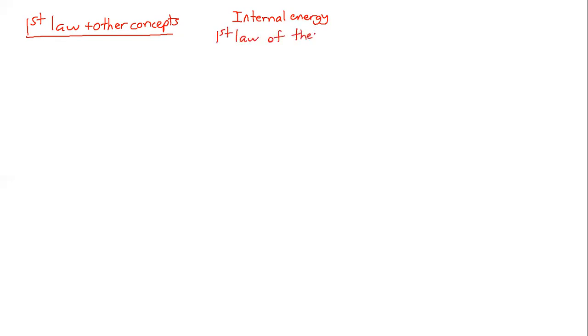is used in process simulation all the time. This is that energy is conserved. You can do energy balances for different types of systems. Aspen Plus actually runs on this. It runs on doing the energy and the mass balances into and out of the different units. So it is important people understand energy conservation and the ways that makes equations.